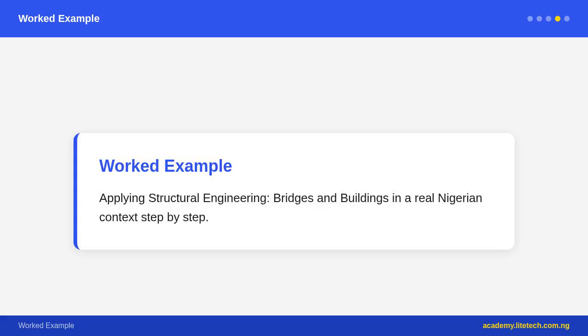Forces, compression, pushing force, tends to squeeze or shorten a member. Concrete is very strong in compression. Tension, pulling force, tends to stretch or lengthen a member. Steel is very strong in tension. Shear, sliding force, acts parallel to surface. Torsion, twisting force. Loads, dead load, permanent weight of structure itself, plus live load, temporary loads, people plus furniture plus vehicles, plus wind load, force of wind against structure, plus earthquake or seismic load plus snow load.